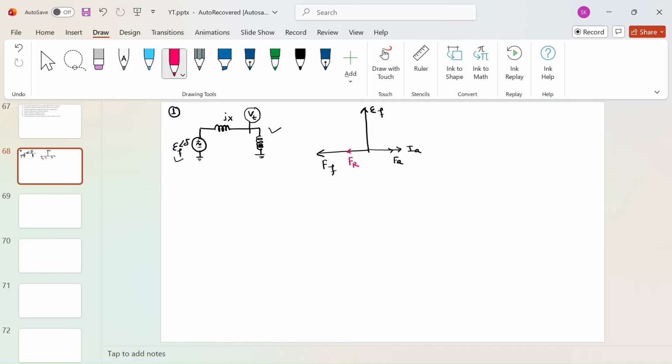And what will happen, that will lead to a reduction in the field excitation, and the effective EMF will also reduce. So to have a sufficient voltage at the terminal, you need to increase your field excitation, and that will increase the resultant EMF. Now for example, your synchronous generator was operating at purely lagging load conditions. In that case, your machine is operating at overexcited condition.